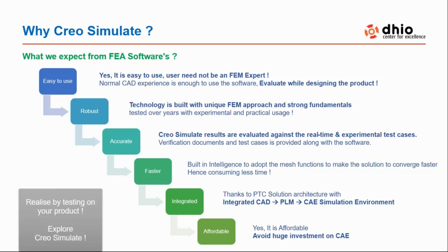It was very much adaptable, and the remeshing capability is very good. And we have the fastest convergence. The software has automatic convergence. The tool has an option called automatic convergence. Since the software deals exclusively with P-type elements, we have faster convergence, and it consumes very little time.